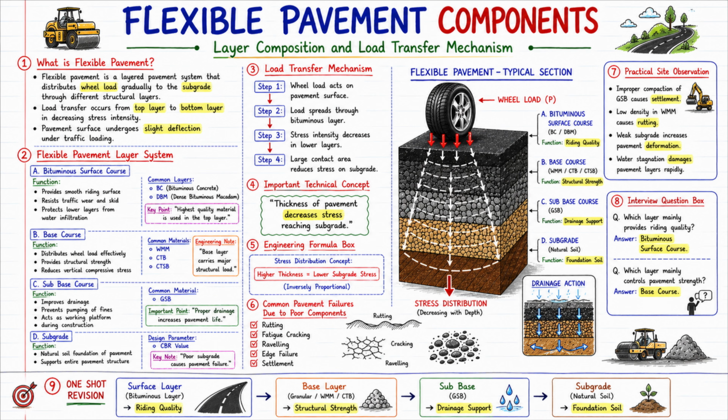An important point is written here. Highest quality material is used in the top layer. And that's absolutely right, because this layer remains in direct contact with traffic. If quality is compromised here, then the overall pavement performance will deteriorate quickly.